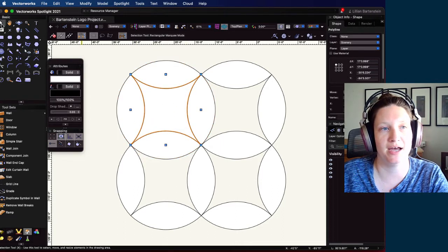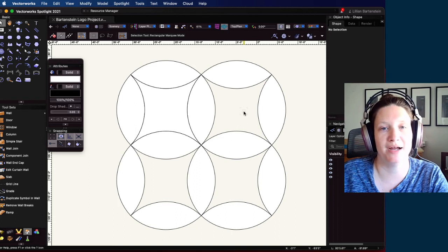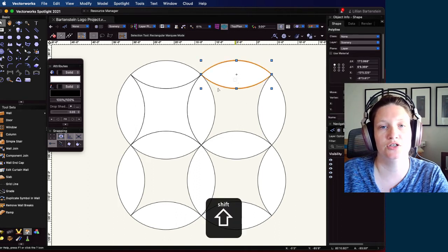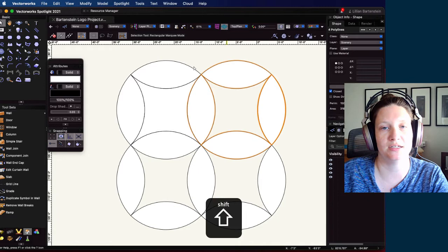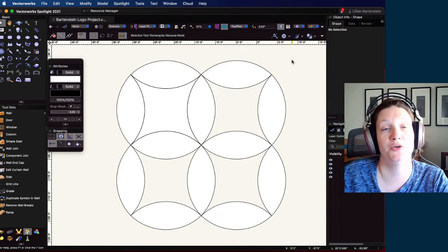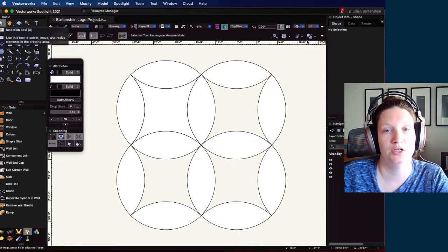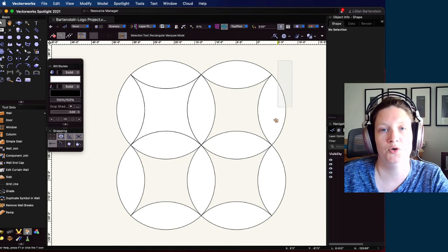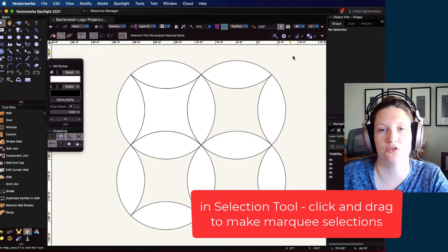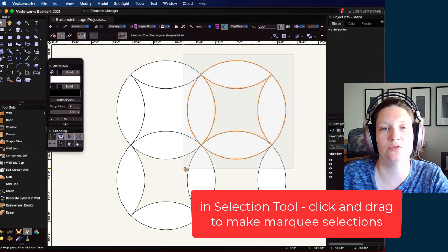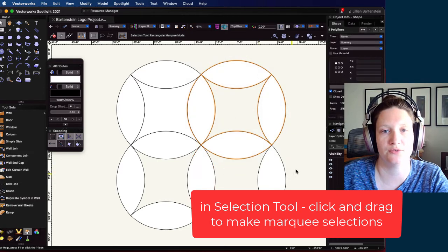Okay, so now I have an inside shape and outside shapes, and I can put a color then where over here I can't. Okay, so my next step will be to do the same thing with the rest of these shapes. So when you are in your cursor, your default selection option will select everything inside of this rectangle, right? So you can grab, as long as you're higher and over to the farther side, you can use that selection rectangle to select stuff, okay? And it'll only select things that were inside of that rectangle.